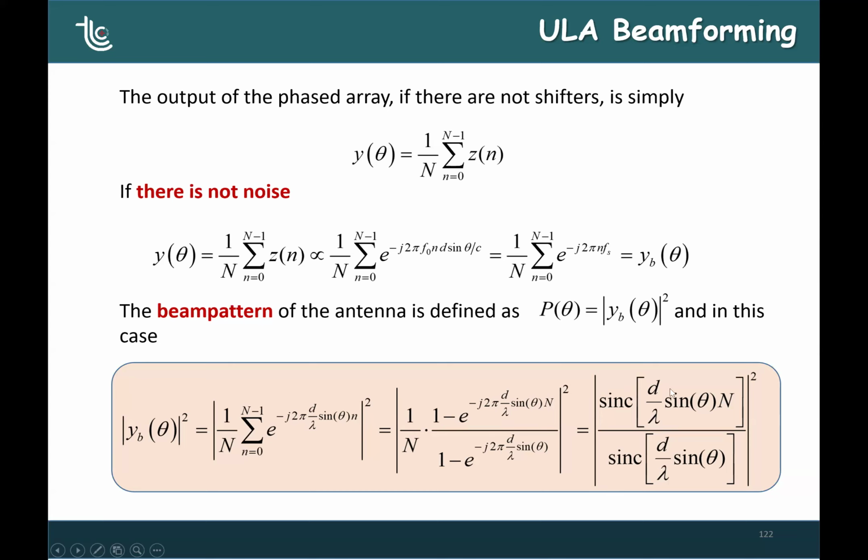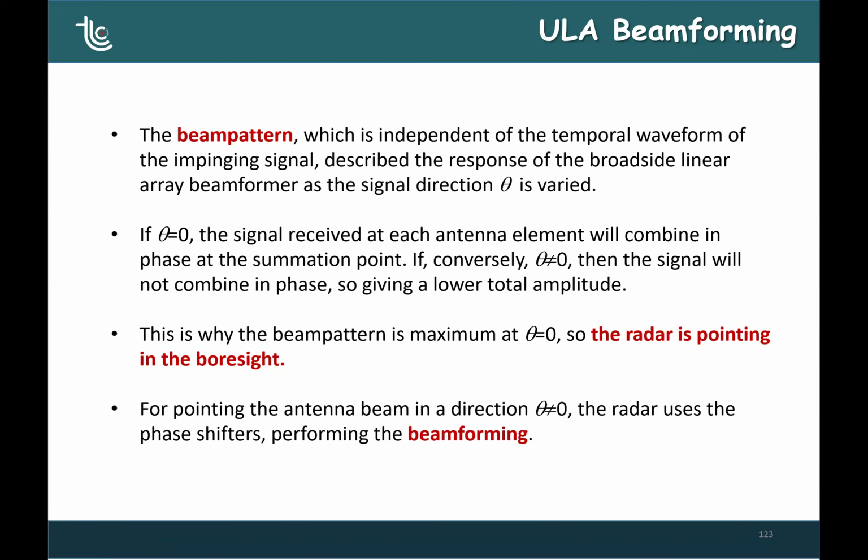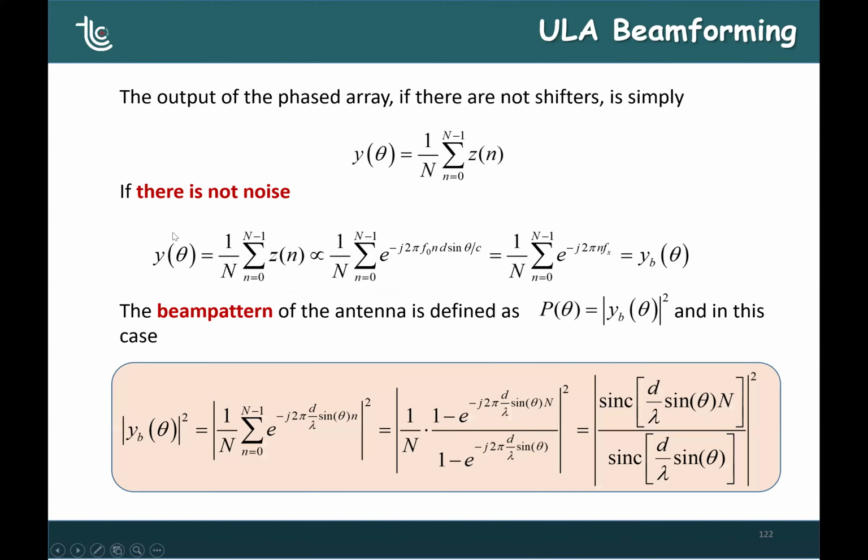They are very similar functions, but you should notice that here we have n in the argument. We don't have the n, but they depend on the angle theta. So the beam pattern is independent of the temporal waveform of the signal, okay? If we don't put any phase shifter, then the maximum of the beam pattern, I will show you the plot, is on both sides.